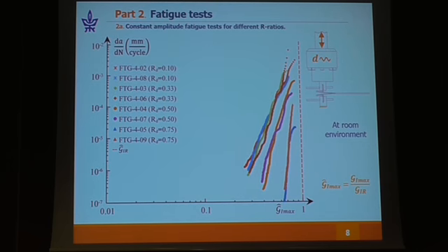Those are the test results plotted with respect to G1 max hat. As you can see, the behavior is as expected from the schematic presentation, and all the curves rise to a common critical value, the normalized critical value, which is why it's 1. The slopes depend on the load ratio, on the displacement ratio, and differ between 6.8 to 25.5, and you can see that the smallest slope relates to the smallest displacement ratio and the highest to the highest.